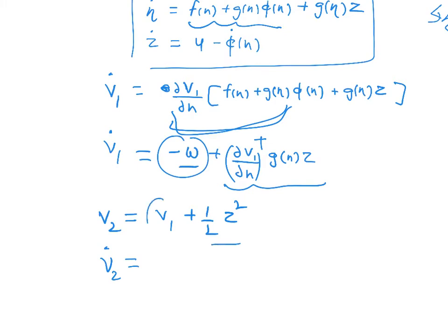See, you made v1 negative definite, so you can keep adding, but this will get complicated if your x1 dot equals x2, x2 dot equals x3, and x3 dot equals u. You have to backstep 2 times. So that will be tricky and a lot of bookkeeping. So if you see, v2 dot will be v1 dot, right, plus z dot, right?